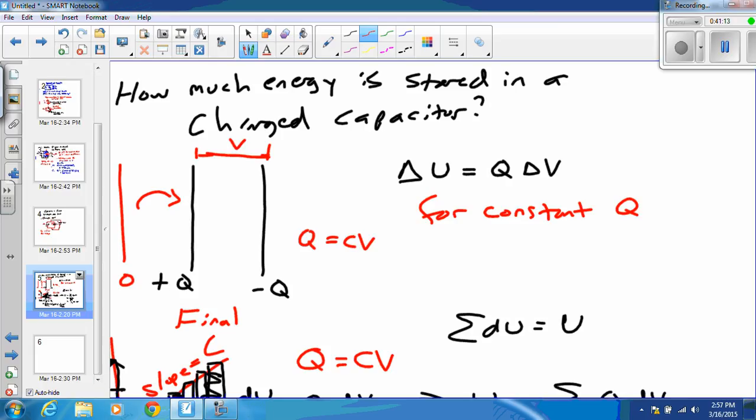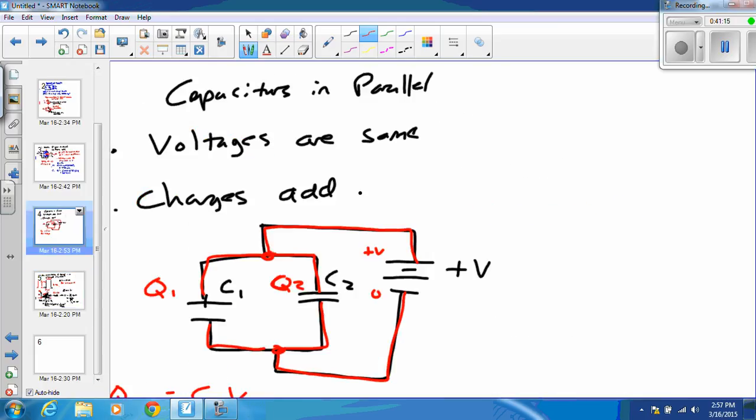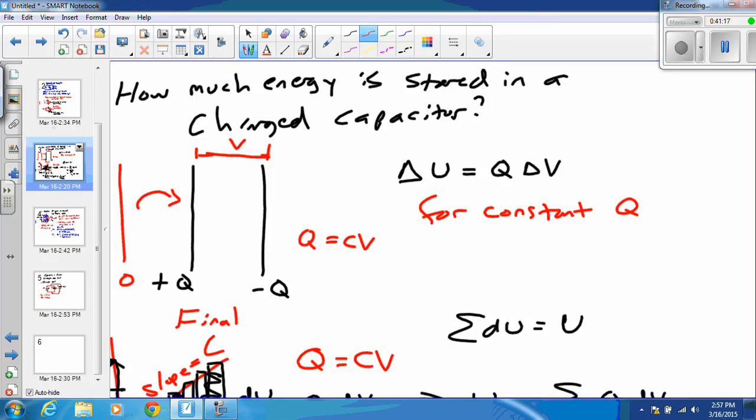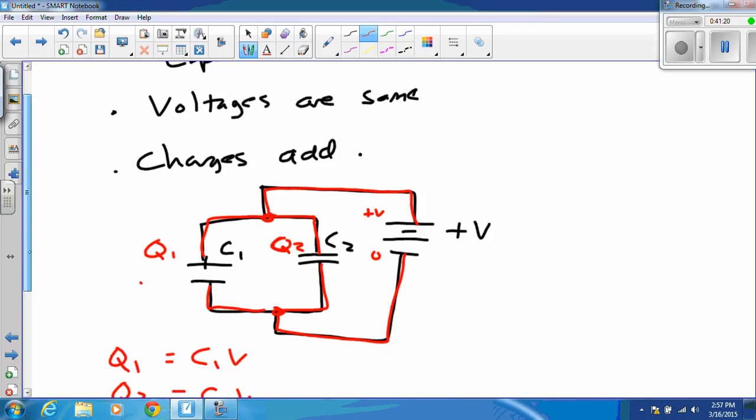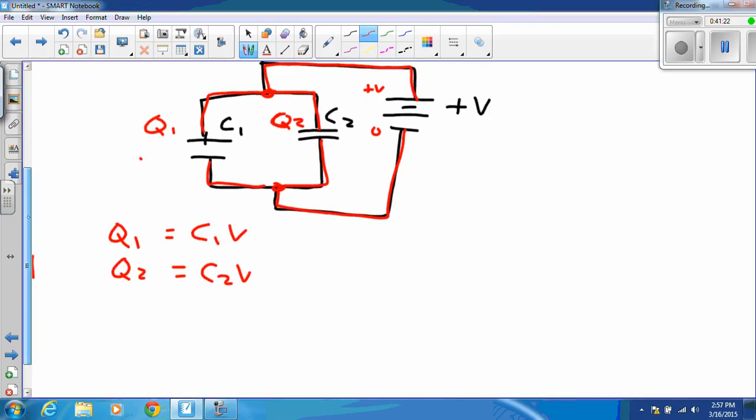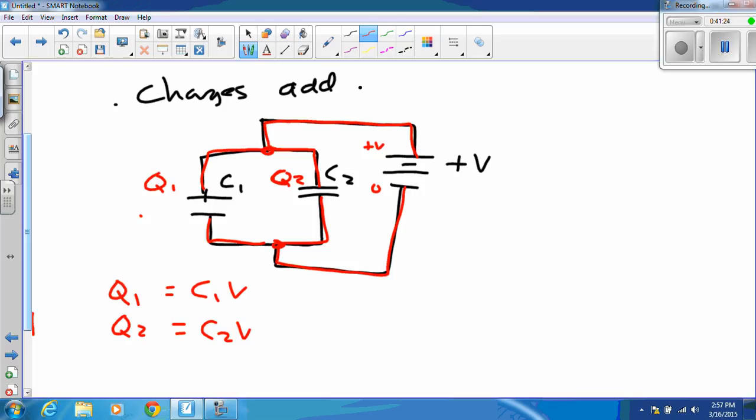So where are we? Oh, that slide is out of order. Much better. All right. So we claim that the capacitors that are in parallel are going to have identical voltages. Let's test that. Come back to our measuring lab. I'm going to turn the power supply off before I swap out my capacitors. Generally speaking, hot swapping parts is a bad idea.